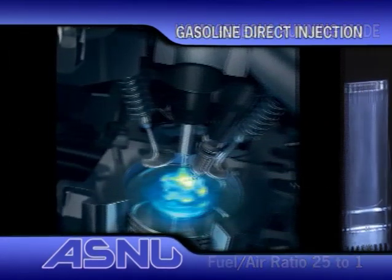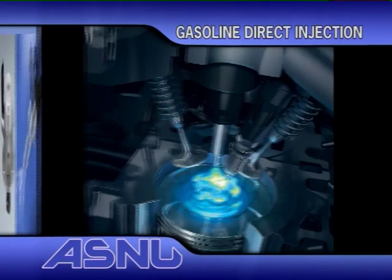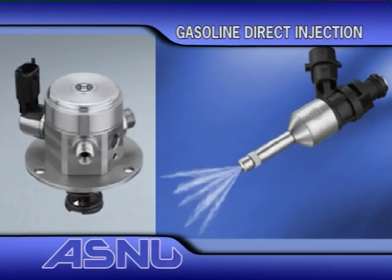As the fuel is injected directly into the combustion chamber, it does require components that will work at much higher pressures, up to 200 bar in most cases. This means that the cheaper produced plastic-bodied injectors and aluminium-cased fuel pumps have now been replaced by high-pressure stainless steel fuel pump and injectors, both designed to deliver very precise quantities of fuel at extremely high pressures for minute durations of time, in some cases fractions of a millisecond.